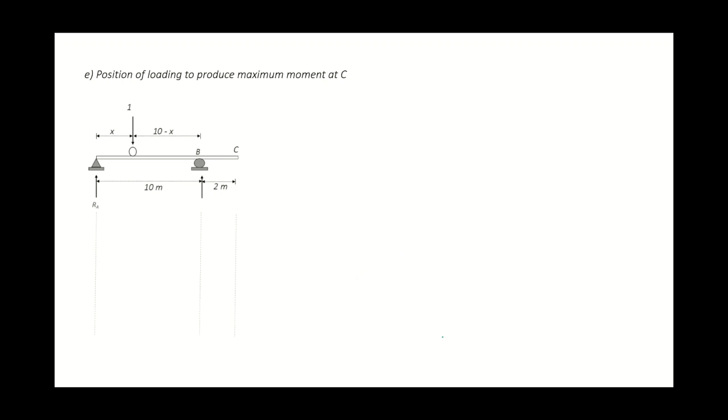Okay, next, maximum moment at C. So, 2 meters from the left support. So, 2 meters. Again, yung cut natin, may internal moment. Yung limit is 0 to 2 ulit. Ayan. Tapos, draw the FBD on the right side. Ipakilagay na din yung moment arm. This is 8 meters. So, 8 meters.